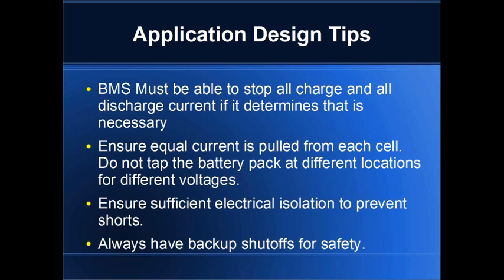It's really important to be able to cut off all charge and all discharge, and the reason is that if you have a small trickle charge or a small amount of discharge that's still happening, you can still overcharge and over-discharge your battery pack. A small load that's left on the battery is particularly bad because you can destroy the entire battery pack. But leaving a trickle charge going is something that can lead to a catastrophic failure too. So both of those are important.